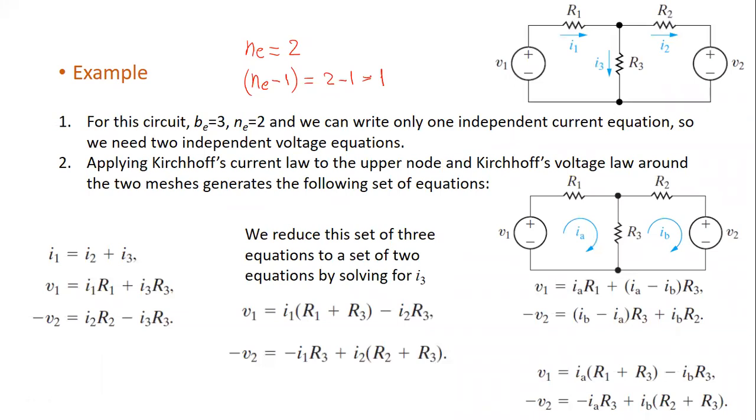So this is if you need to go with the nodal voltage analysis, right? But now we are not thinking about nodal voltage analysis. We need to think of how to find the currents. In R1, I have a current I1. In R2, I have a current I2. In R3, I have a current I3. And I gave these directions. I want to find the values of these currents without using the nodal voltage technique. I want just to use Ohm's law, KVL, KCL, and try to find the 3 currents.